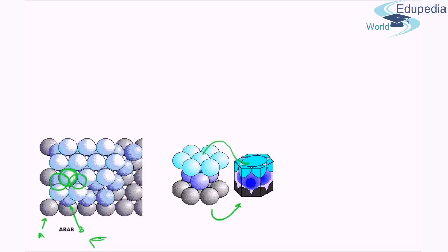Now for the hexagonal packing, what is the coordination number again? You can again think of it in the same way as the FCC. So if you take this atom, 6 atoms here, 3 atoms at the bottom, 3 atoms will be at the top. So for the hexagonal packing system also there will be the coordination number of 12. What will the packing fraction? A similar argument to that of the FCC can be given and said that HCP will also be 74%.